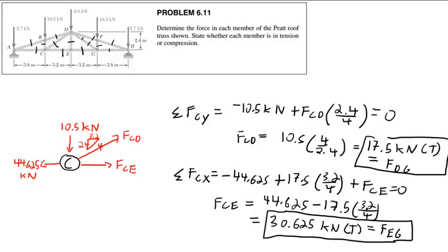That's all there is. So the number of solutions is equal to the number of members in that case, if the truss is statically determinate. If you were to count your solutions here, would you have... Well, yes, because we literally solved for every member. So let's see, where it says m plus 3: the number of unknowns which can be determined from the free body diagrams of the pin is m plus 3. Okay. Again, that's just part of the solution, not the whole thing.